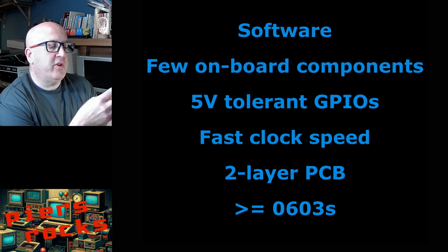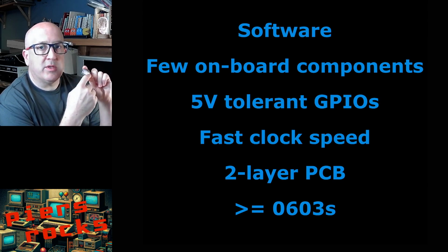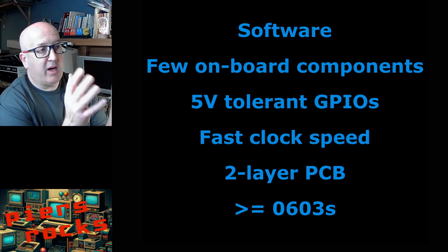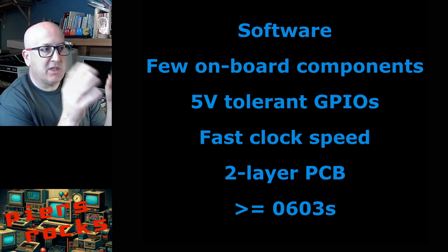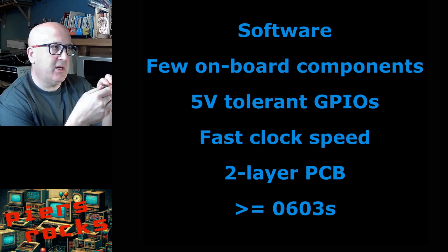The only way I could have used a non-5-volt tolerant microcontroller would be by putting components on the other side, which I've already talked about. I wanted to avoid putting anything on the underside. I wanted to keep it to a single layer component design.